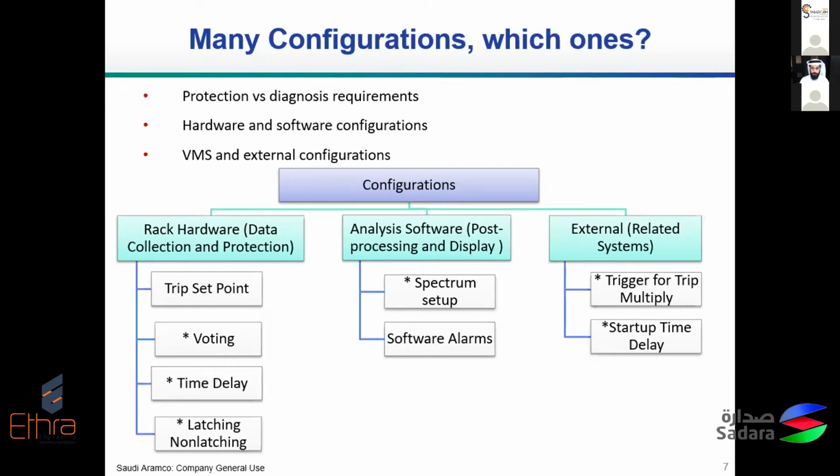So these details are important for you as a rotating equipment engineer or plant professional, in order to understand why the trip took place, and why it took place in this manner. And if you have an equipment that could behave in a certain way, you should design your protection system, your configurations, to be a balance between overprotection and underprotection.